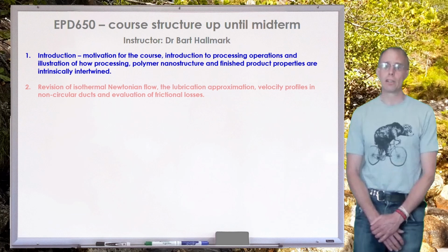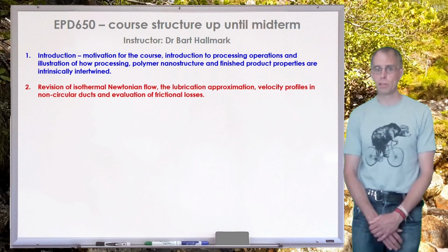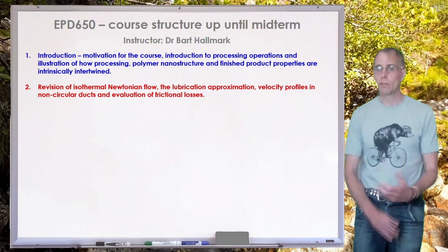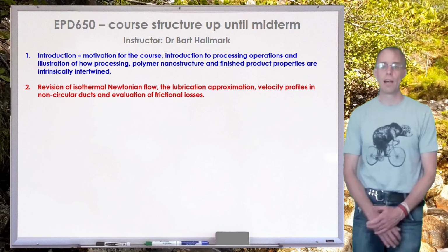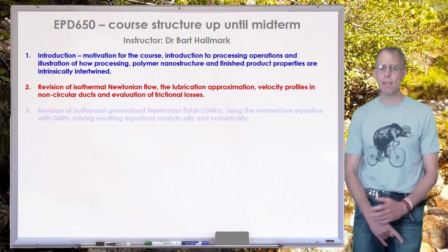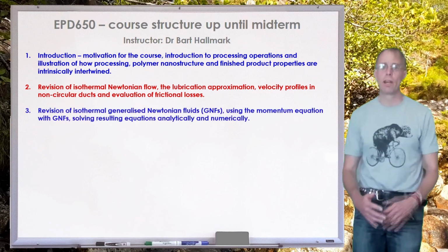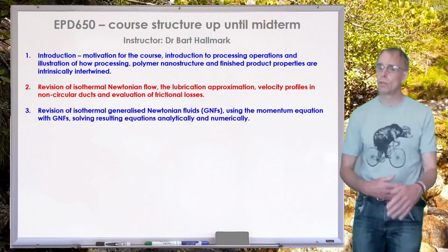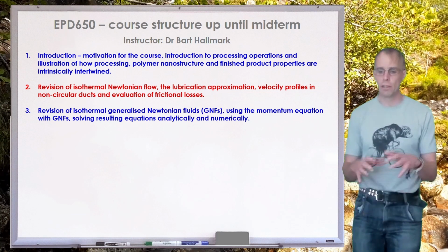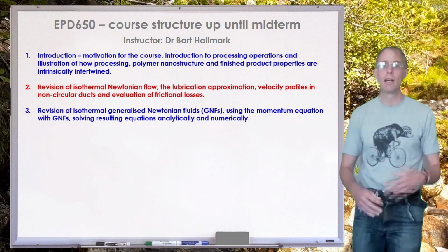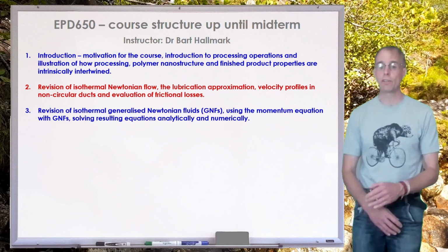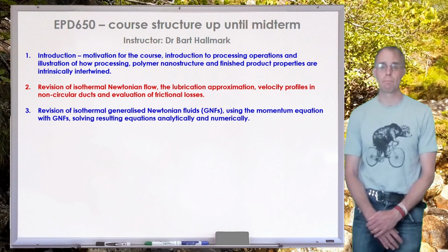The second lesson, I'm going to be doing a revision of isothermal Newtonian flow, including things such as lubrication approximation and looking at velocity profiles in non-circular ducts and some methods to evaluate frictional losses in pipework. The third lesson will develop on this. I'm going to talk about isothermal generalized Newtonian fluids, again using the Cauchy momentum equation as the most fundamental principle, and I'm going to show you how to solve the resulting equations both analytically and numerically using Mathematica.